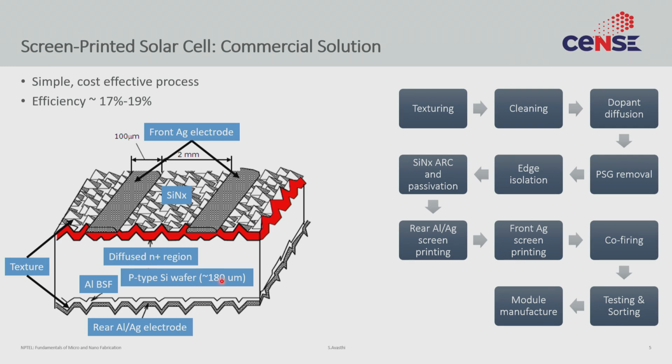We see a p-n junction that is required. All solar cells have p-n junctions, great. But we see that there is only one n-type diffusion, right? There is no n plus. And that is to save on one diffusion. One less diffusion means cost saving. We realize that there is no p plus layer, but something called aluminum back surface field.